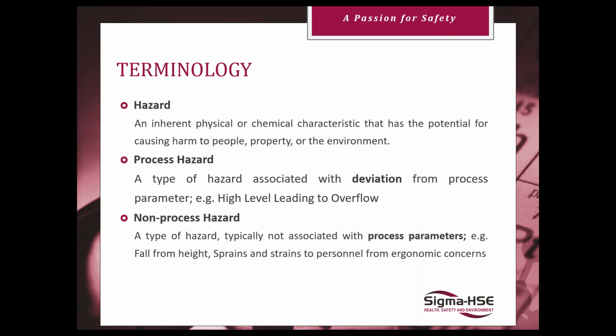All right, so your hazard: an inherent physical or chemical characteristic that has the potential for causing harm to people, property, or the environment. So you're looking at if it's flammable, if it were to be released, is there a potential for a flash fire, an explosion, a deflagration? Is it toxic? Is it dangerous to the environment? If you were to have runoff into an adjacent waterway, are you looking at a fish kill? Or if it's something really bad, are you looking at, say, a permanent Superfund site type of thing? And ranking what type of hazard each material in your process has, and then the realisticness of that.